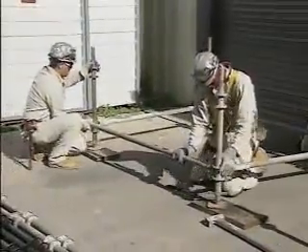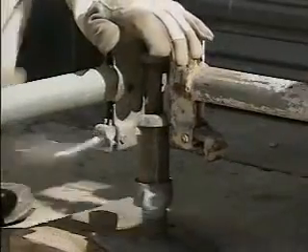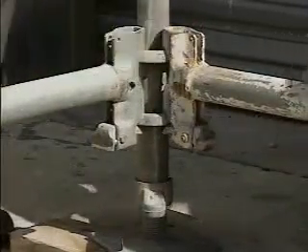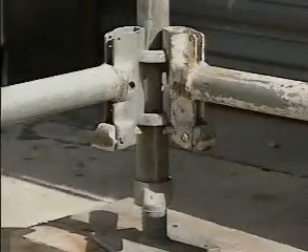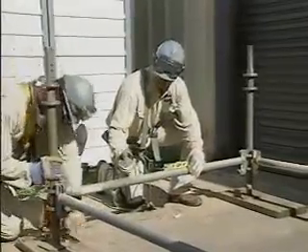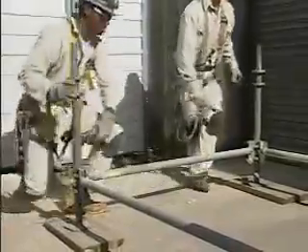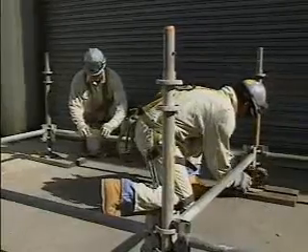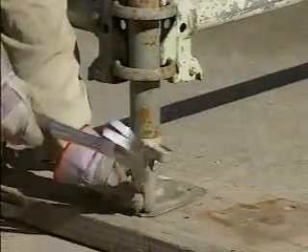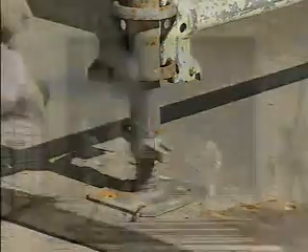Then, the first of the horizontal members are connected between the starter collars. The horizontal members are secured to the starter collars by driving in wedge pins on the end connectors. This locks the end connectors of the horizontal members onto the locking rings of the starter collar. If the scaffold isn't level, the builders adjust the screw jacks as needed to make it level. They check each horizontal member this way until the lower framework of the scaffold is level. Then they nail down the base plates of the screw jacks to the sills to secure them.